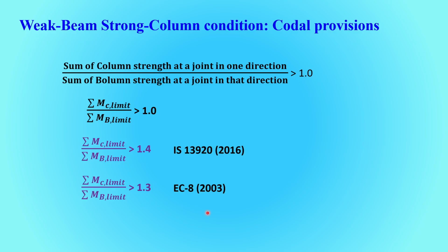Now in research, my finding is that in high-rise buildings this value should be much higher to arrest the failure of the columns. You may require a value of 2, 2.5, 3, etc., so that the column is not failing. This happens because of the amplification of the action effects towards height in high-rise structures. So there you may require more than these defined values of the limits of the ratios given in the code.